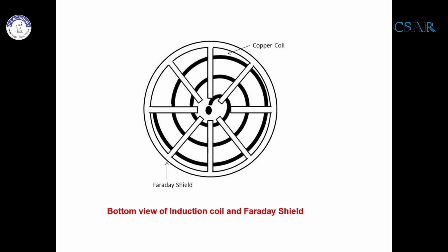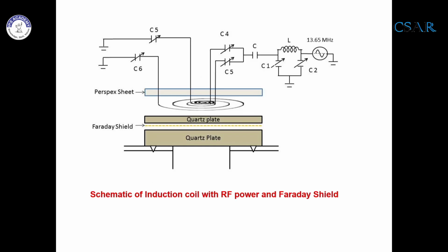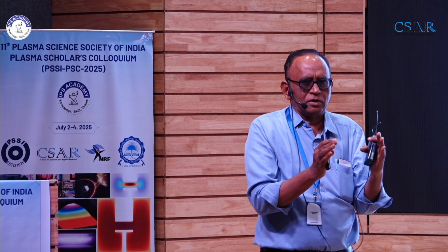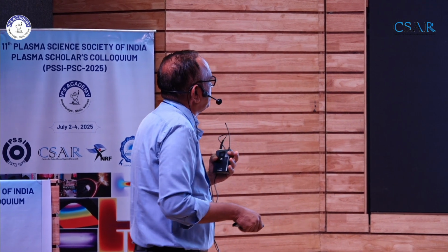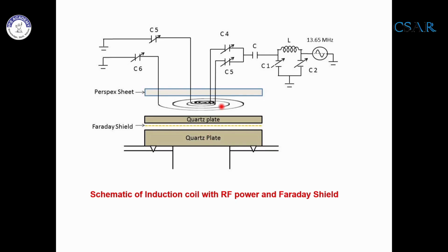Now, what is happening actually is that these antennas are outside the chamber. They are not in the vacuum. There is a dielectric plate, and as I told you in the previous example of RF sputtering, the RF dielectric loses its impedance. So when these dielectric plates lose their impedance, the RF field will try to couple with the plasma species that are generated here, and that means RF voltages will leak into the plasma. We don't want that situation, because these sources are meant for processing semiconductor material.